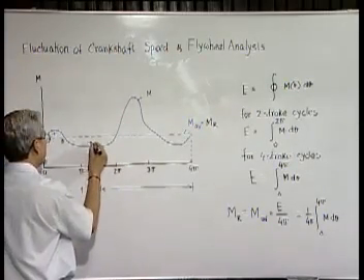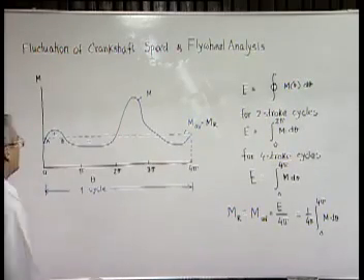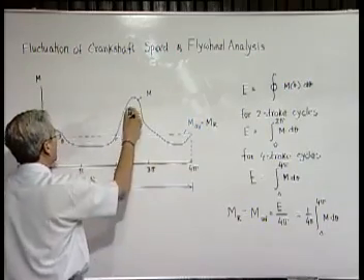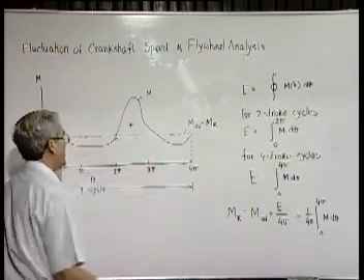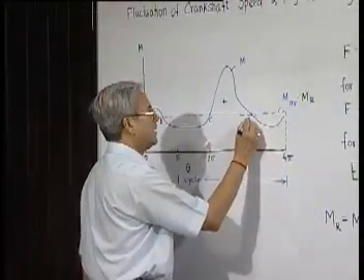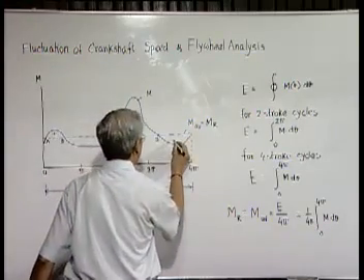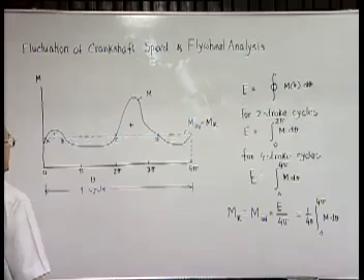So energy is depleted and kinetic energy goes down up to a point C, where again the driving moment becomes more. That means it starts accelerating the system, adding energy till the point, say D, where again the driving moment becomes less than the resistance, and so energy is depleted, reducing the speed. Again it goes back to point A.